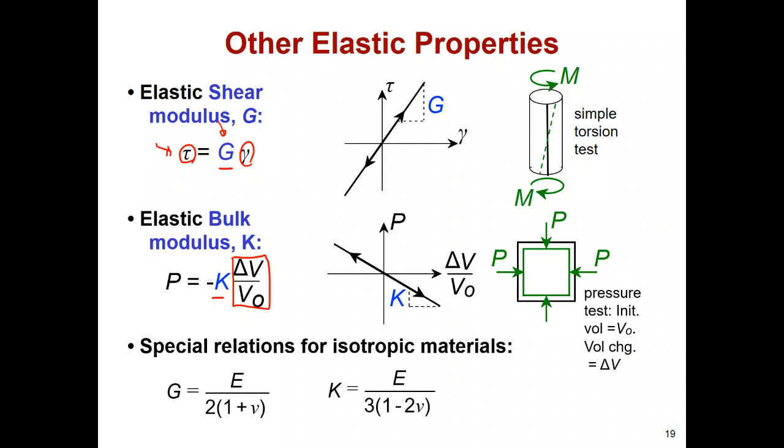Then in the next solid mechanics course, maybe next year, Professor Yang in our department will teach those topics, so after learning them you can easily understand it. Anyway, the shear and bulk moduli are strongly related to Young's modulus and Poisson's ratio. This is because the solid structure shows a linear relationship, and from the atomic scale point of view, the atomic bond distance affects those macroscopic behaviors.